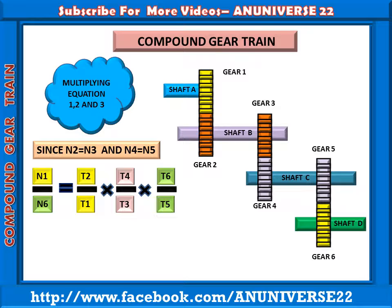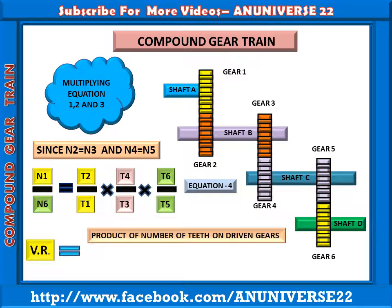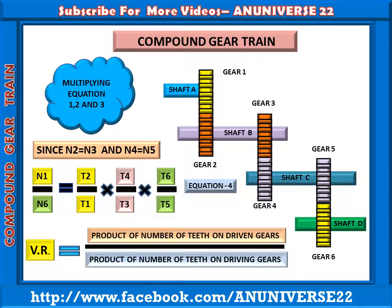Here the number of teeth on gears varies according to the diameter of the wheel. Here gear 2 and gear 3 are both on the same shaft. Gear 2 may be small and gear 3 may be a big gear. So there is a variation in the number of teeth on the gears. So this is equation number 4, and the velocity ratio is equal to the product of the number of teeth on driven gears to the product of the number of teeth on driving gears.